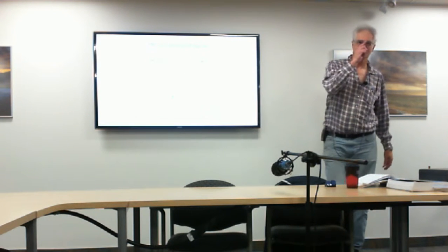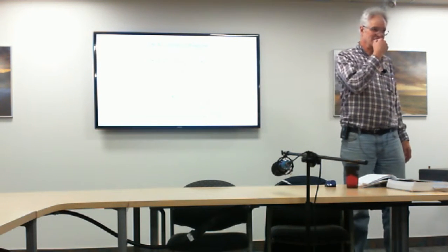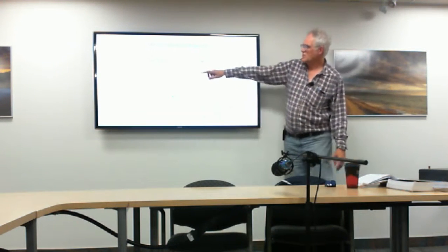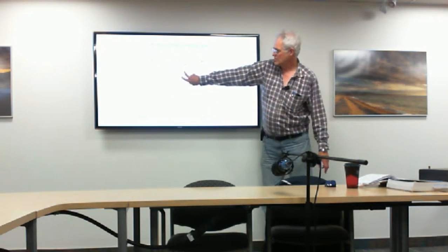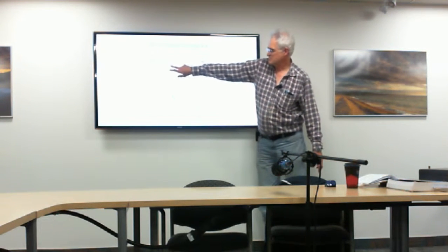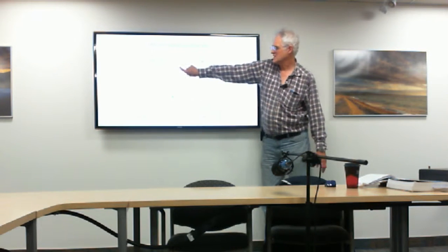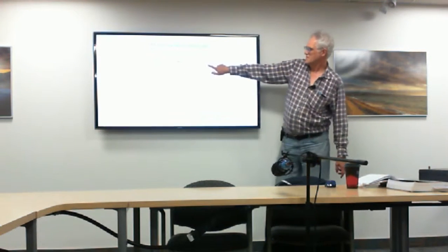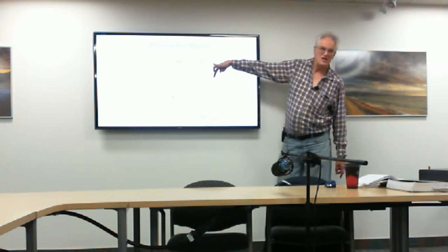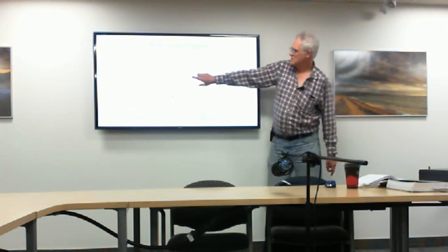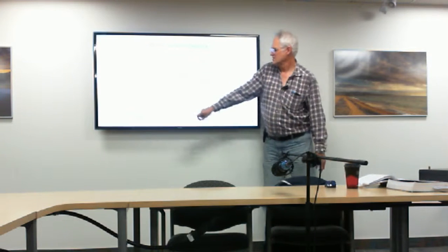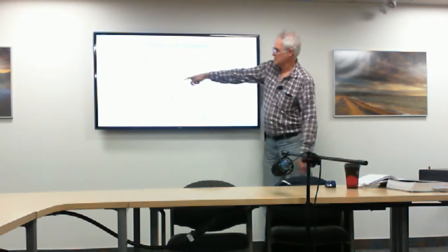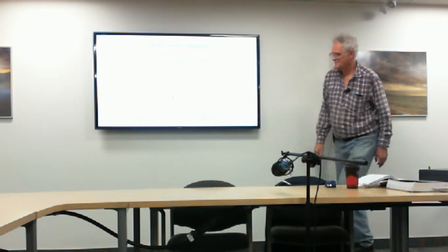So the high frequency oscillator is for the RF frequency. Yes, this is a fairly high frequency, going to be fairly close to our received frequency, because we need to mix the two down to give us our intermediate frequency. So these two frequencies will be fairly close together, and the other one is going to be way lower. So the beat frequency oscillator is working with audible frequencies?